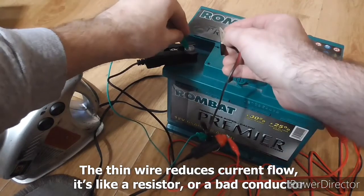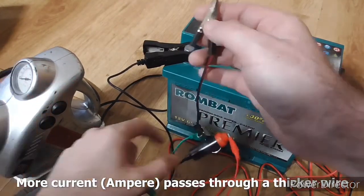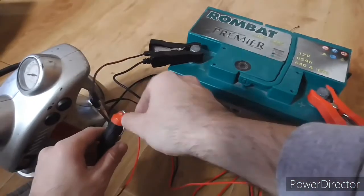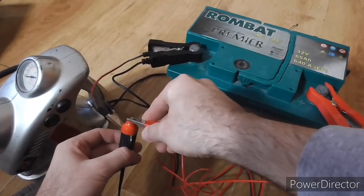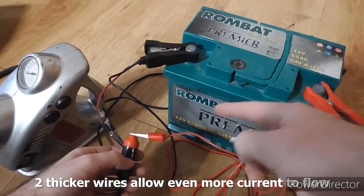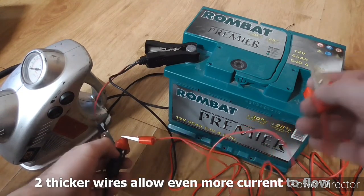There's a thin wire That's a thicker wire, so it makes a large difference. Now I will replace both wires. The difference is not huge, thickness wise, but conductivity wise it is. That's a huge difference. So before only the right side, the plus, was blocking the current. Now both of them are conducting much better.